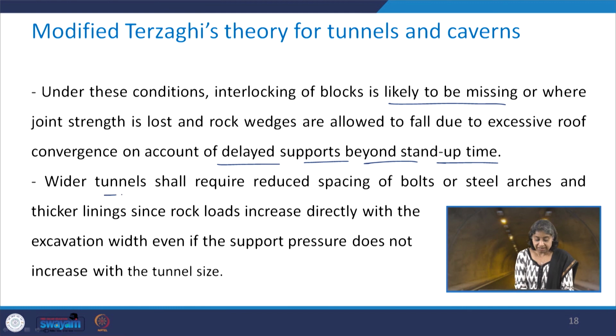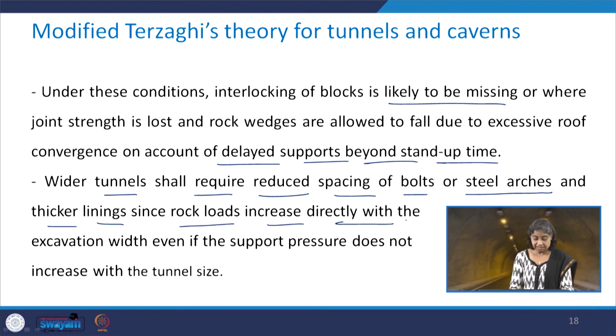So, the wider tunnels shall require reduced spacing of bolts in such cases, or steel arches, and maybe thicker linings, since in that case the rock loads increase directly with the excavation width, even if the support pressure does not increase with the tunnel size.